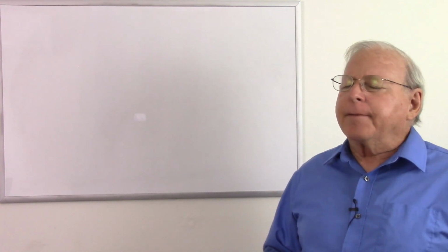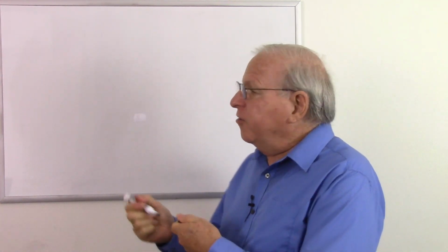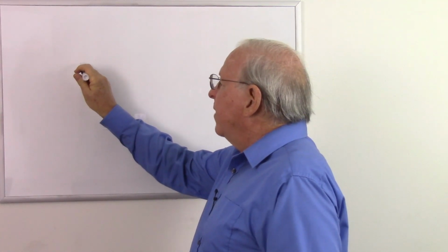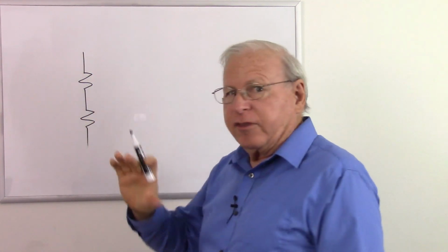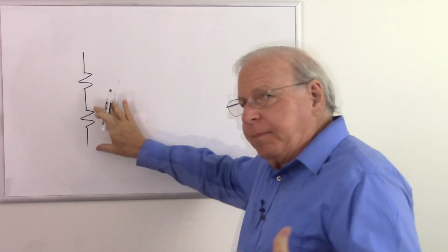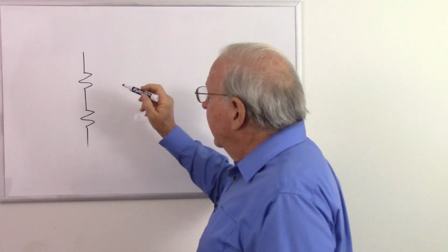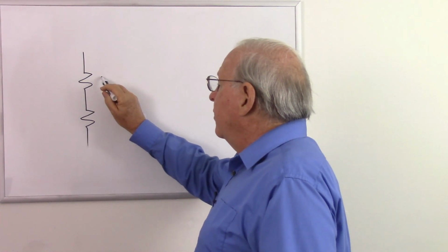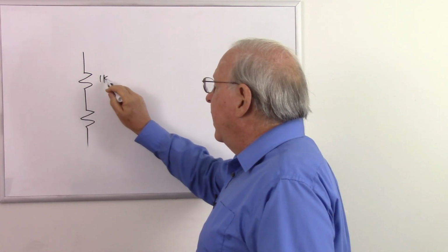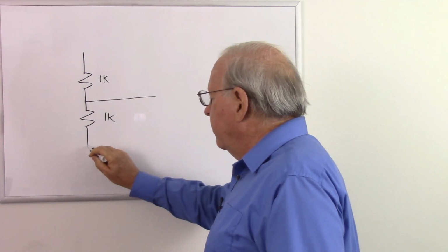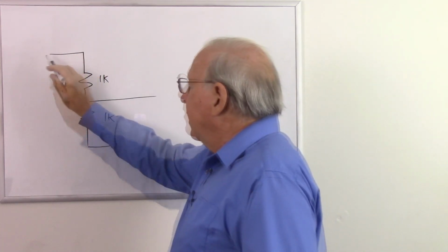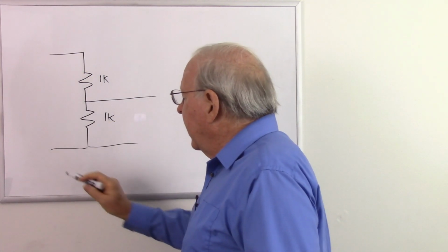So why is that? Well, remember, in series circuits, if we have a voltage divider, here's two resistors, which represent the impedance of the microphone and the impedance of the mixer input. And let's say these were equal. Let's just make it 1K and 1K. So this is going into the mixer. There's our common ground. That is coming from the microphone.